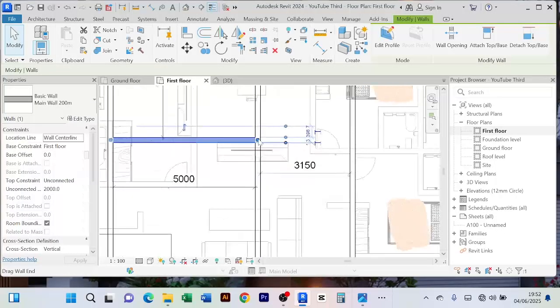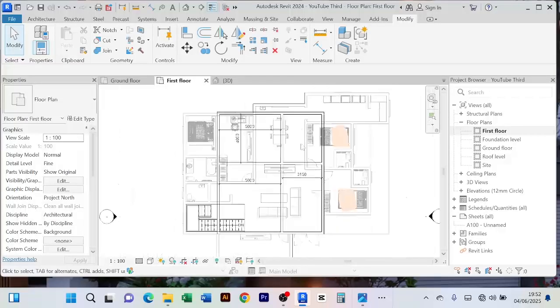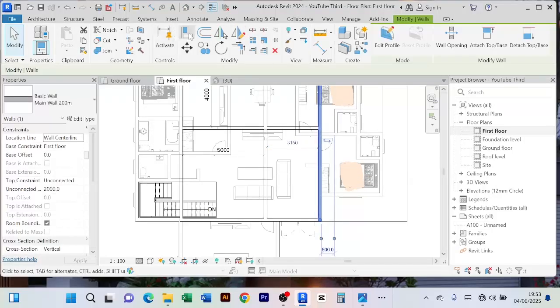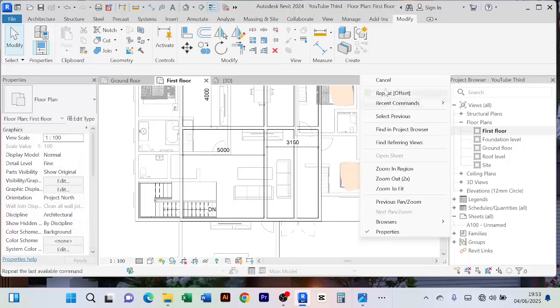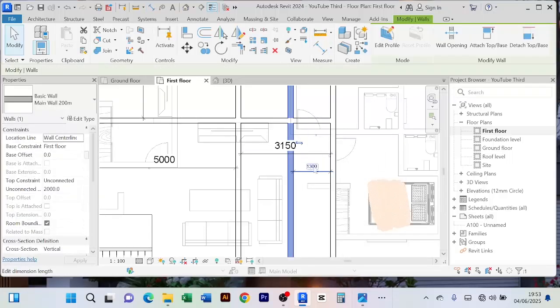So I think I want this wall to extend here, so that we shall have this part. This one will be an office. Then we can have a common washroom here in the middle. So I'll offset this room. I'll offset it by let's say 1.5. 1.5 here. Let's see what we have by measurement. So it's showing here 1.3. Click on it, I'll say 1.5,